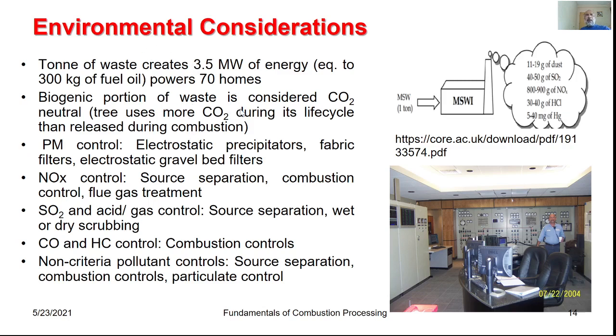In order to have this particular environment protected, the particulate matter is controlled through electrostatic precipitators, fabric filters, and certain gravel bed filters. The oxides of nitrogen, oxides of sulfur, and other gases such as carbon monoxide and hydrocarbons need source separation as well as combustion control, and also flue gas treatment, in order to protect the environment.